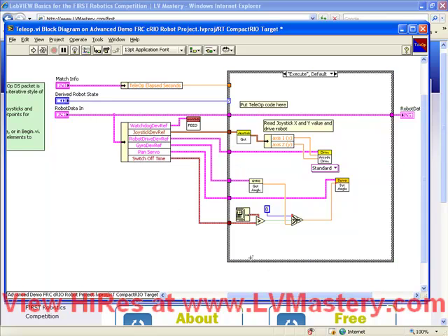And it's a very common pitfall, especially when you're doing a lot of LabVIEW programming, to forget to go back and fix your wires or to do it all later, at which point it's going to take an awful lot longer. And you'll observe once you get quick at it that it doesn't take any longer to put the wire exactly where you want it than to just drag it directly from the source to the destination.